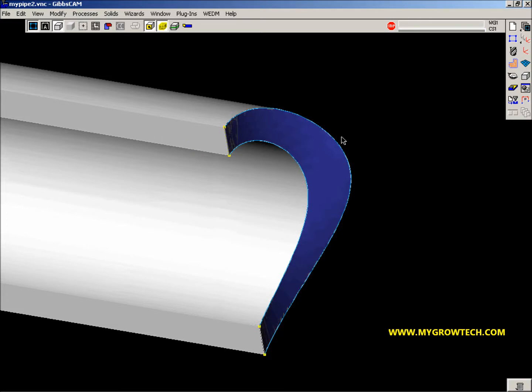What we need to make sure is that the sheet side is correct. So we're going to check the sheet side. Every sheet has a plus and a minus side. Plus being the side we want to cut, minus being the underside of the sheet. In this case you'll see red, which means we're on the minus side. If I was to put my toolpath on this sheet the way it lies now, toolpath would be on the wrong side of the sheet.